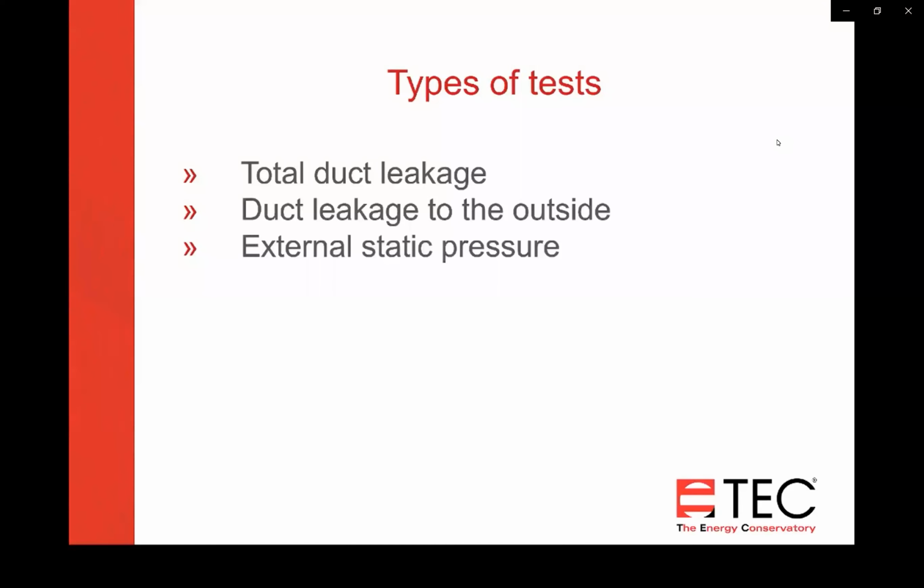External static pressure. If you're doing duct sealing, it's important to know what this is and how to take those measurements. Sealing up ductwork will raise the static pressure in the duct system, and you don't want that to be beyond what the maximum for your system is. So doing that is important.